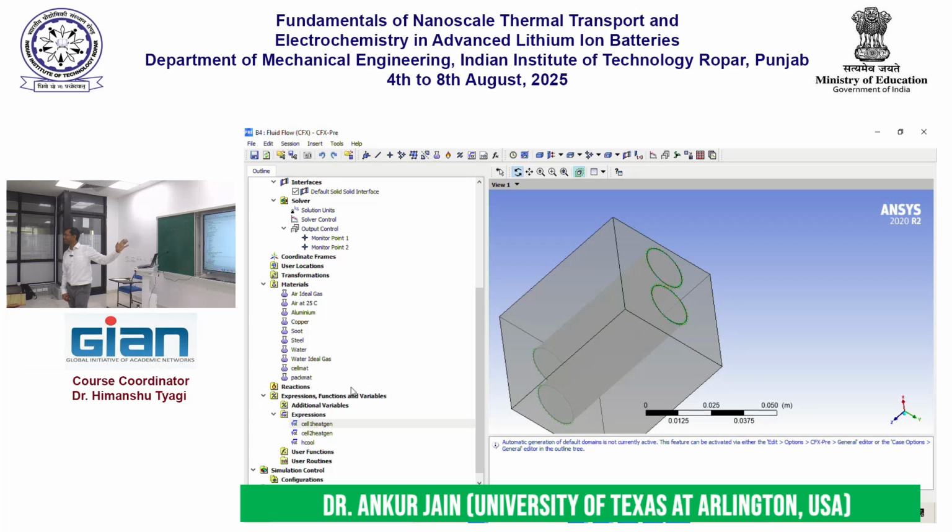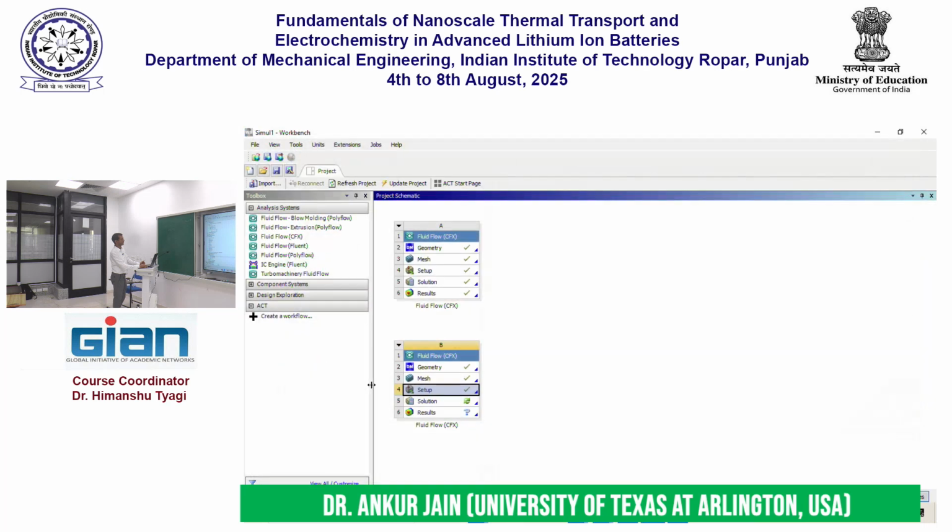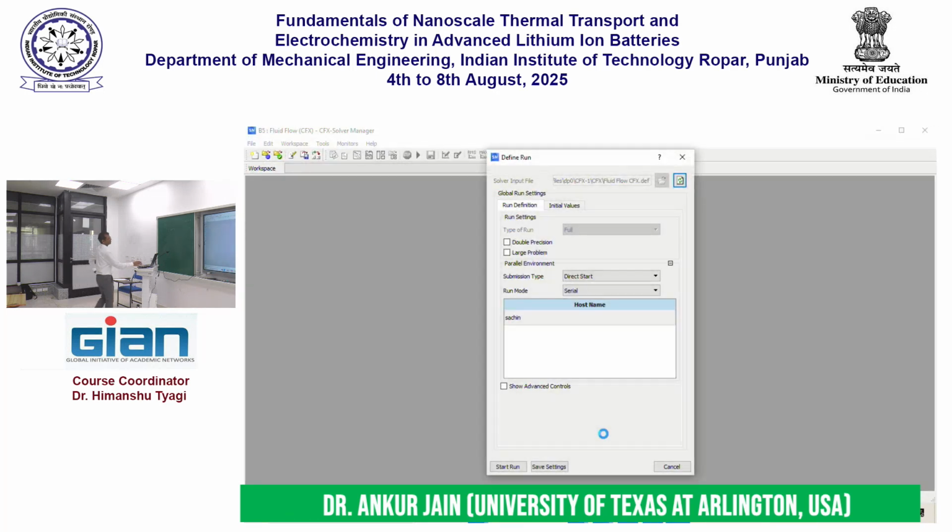And see, numerical simulations are easy in the sense that having set all this up, now you can start asking questions. What happens if the cell has a different diameter? What happens if the conductivity is different or the heat transfer coefficient is different? You can always come back here, change it and run your simulation again. Okay? And oftentimes if the geometry is complicated enough and if we are not able to derive an exact solution for it, like we have done for simple geometries, then numerical simulations is your only option. All right, so let's finish this here, and I'm ready to run this. I suspect that this simulation will also not take a long time to run, not more than a minute or so, perhaps even less.